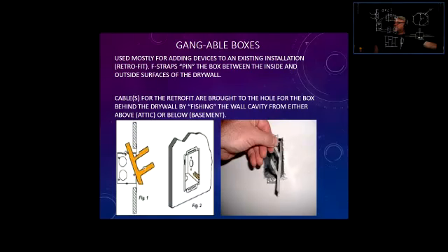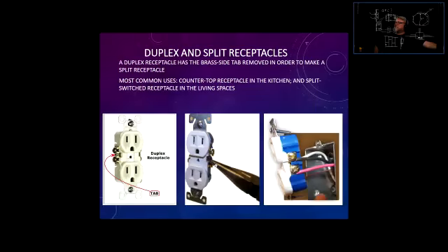And those are also a common thing that is stored in the working vans. They just buy them by kilograms and stock them there, because you never know when you might need one. Very nifty device, right? That will help you to install a device box in a drywall, so that it's only going to be held by the drywall between the two studs, and it's still going to be okay.